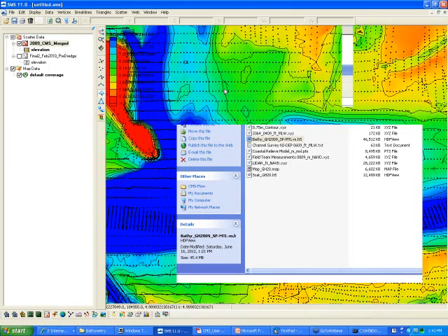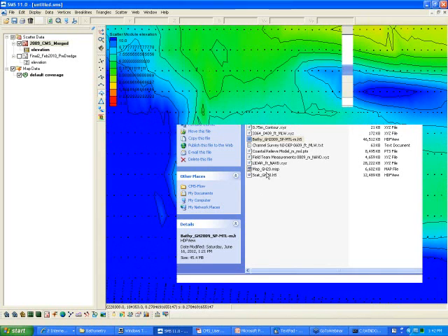This survey here was very high resolution and only along the transects, right? But the transects were spaced 300 meters apart. If you do triangulation with that, you end up with long, very thin triangles, and it looks noisy. Even here, you can imagine if these points were spaced closer together, these effects would be even worse.